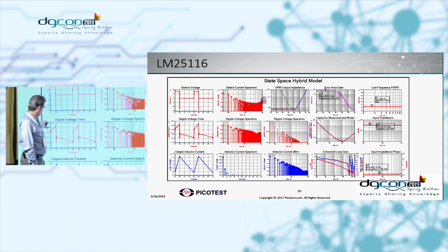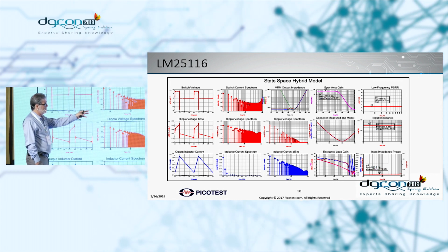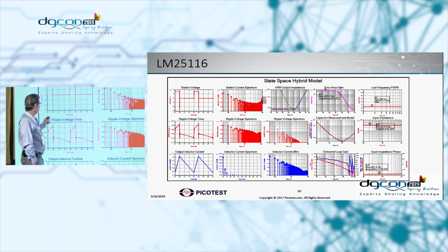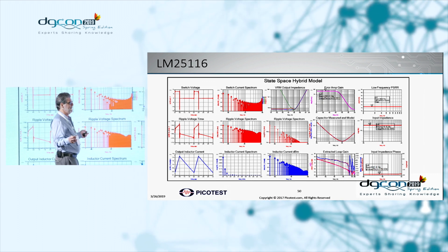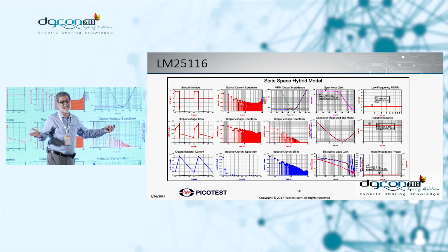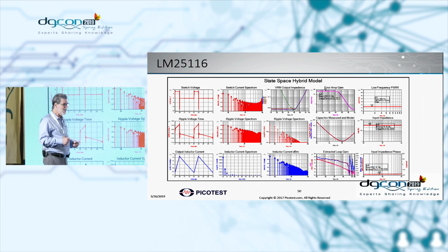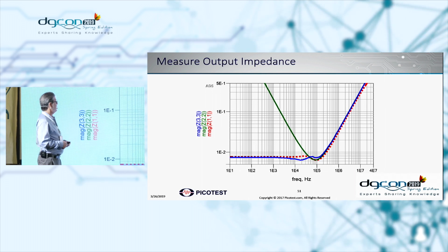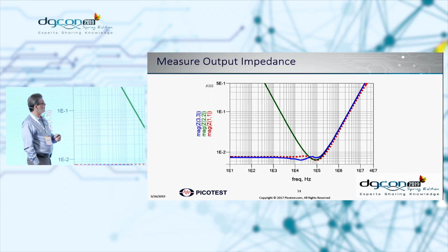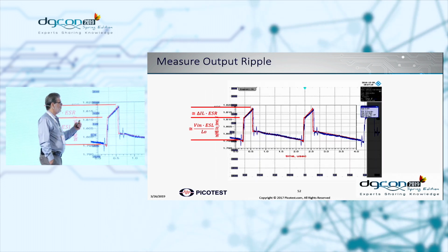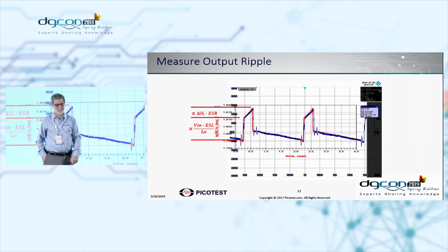Now we look at the output spectrum. The output gives us all of the displays: the impedance, the PSR, the capacitor measurements, inductor current, switch time, ripple voltage, all that stuff. But again, how do you know I'm right? I played that funny game of reconstructing voltage waveforms so you could see ripple. How do I know that's right? Well, I can compare the impedance, and I know that's right because I did my measurement and my simulation and those agree really well. And there is my ripple waveform, and again, you can see that agrees really well with the exception of the little blips.